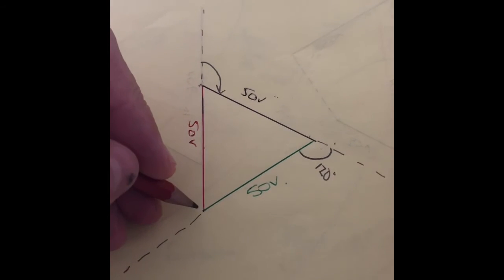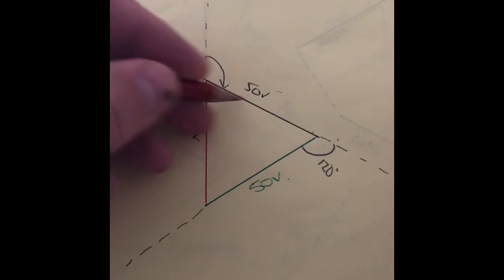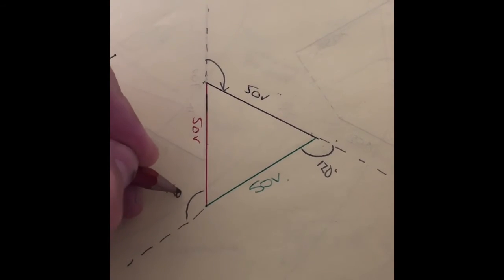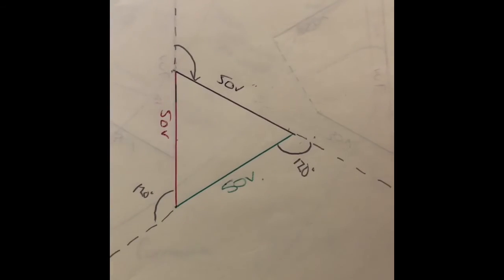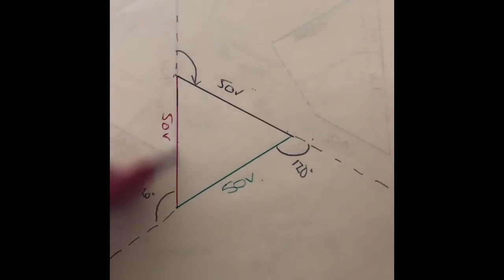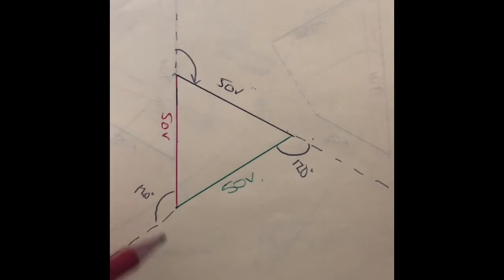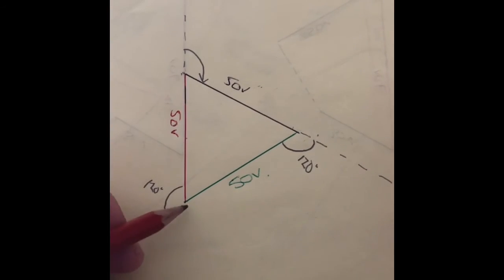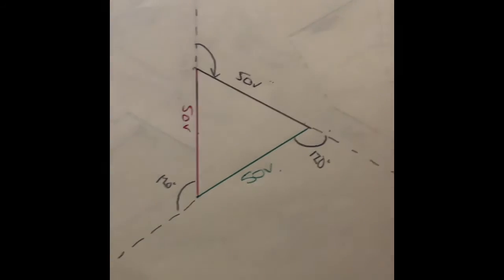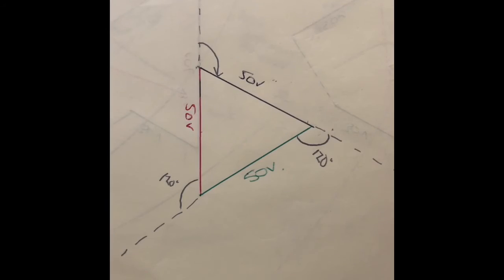And we find now, because it is perfectly balanced, it creates our perfect triangle. Again, just to show our 120 degrees on there. So now we have a perfect triangle. We can see here that these are perfectly connected and there are no resultants whatsoever. There is no gap at this joint. If there is a gap, that means that we do have a resultant force being sent down the neutral.